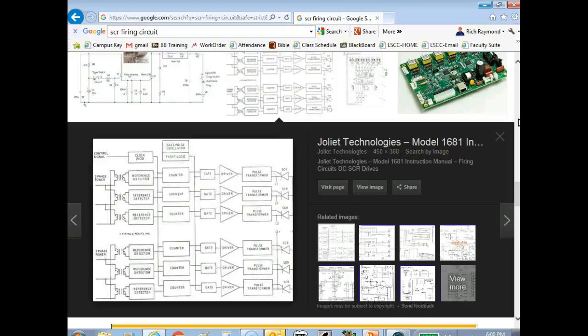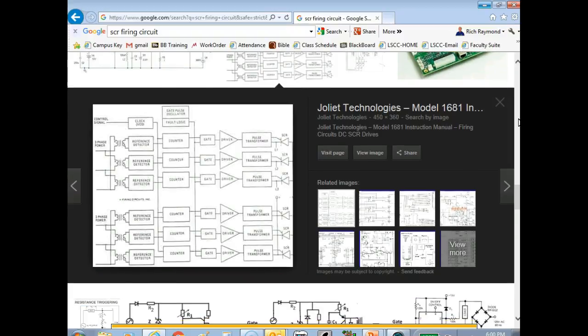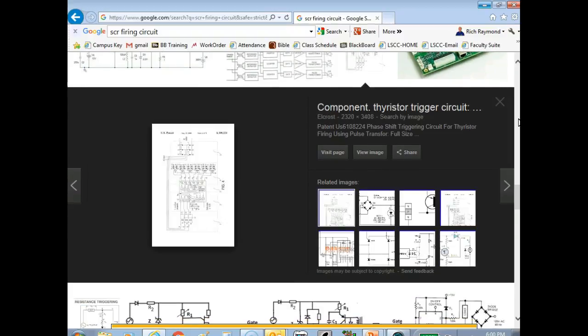All the rest of them were on big old heat sinks. So, water cooled, yeah, big packs. And why they water cool them, of course, is because of those big heat sinks. You get up in there at 600-700 amps, way up in those high power units, the heat sinks to get the heat away from the SCR are going to be huge.